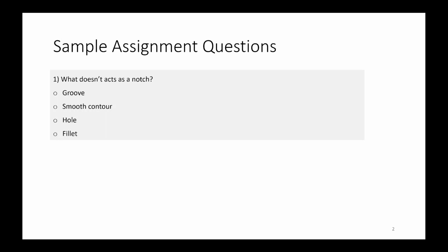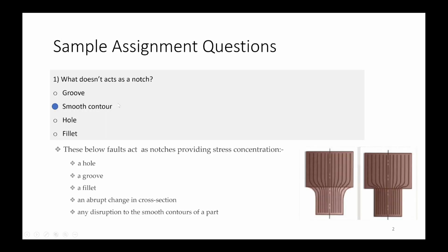So first question is, what doesn't act as a notch? A notch acts as a stress concentration point in your material design. Your options are a groove, smooth contour, hole or fillet. Your answer will be smooth contour because it won't be increasing your stress concentration.